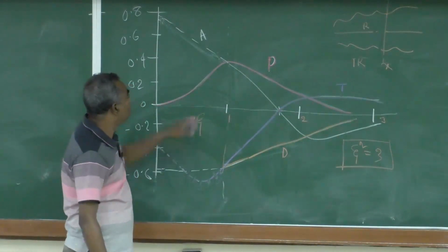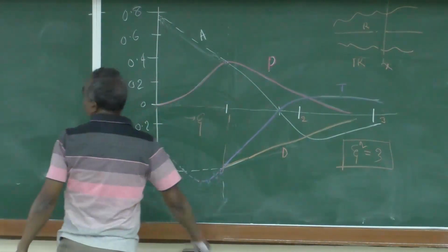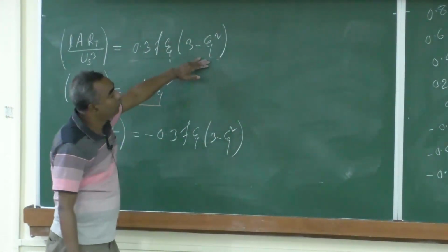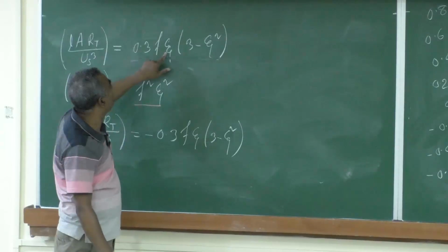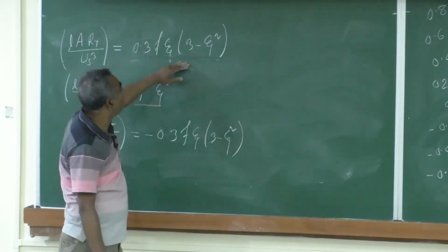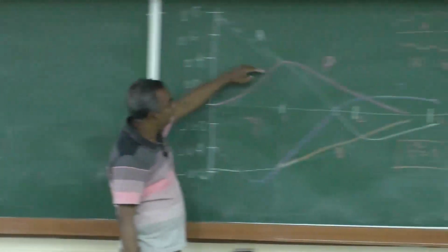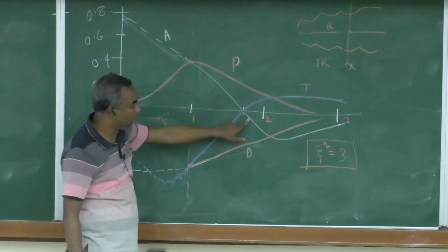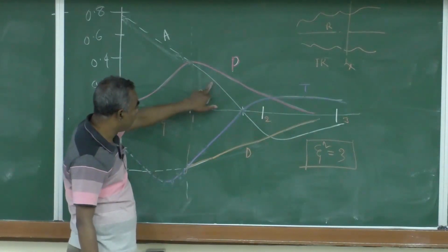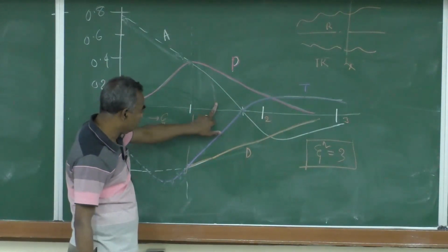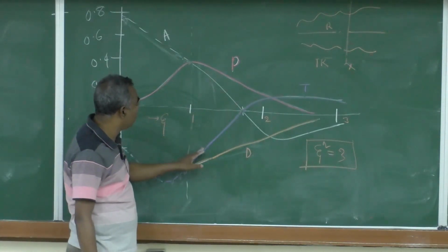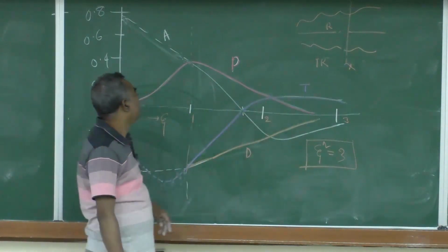Okay. Now, advection: beyond j equal to 1, with increasing j, advection is going to reduce, and at this particular point it is going to be negative. So, from this point onward it is trying to deposit the turbulent kinetic energy towards the outer side, and this turbulent transport is going to somewhat balance it.